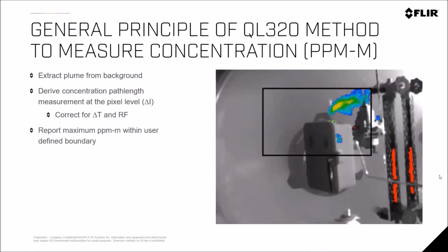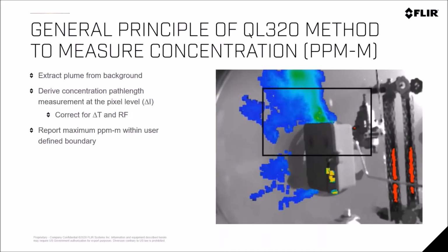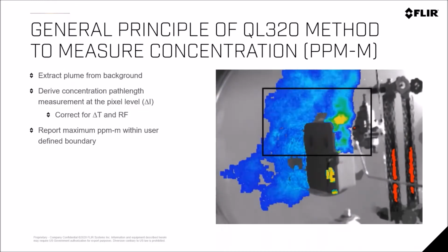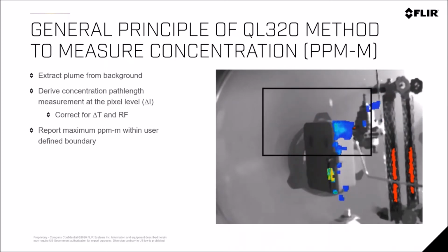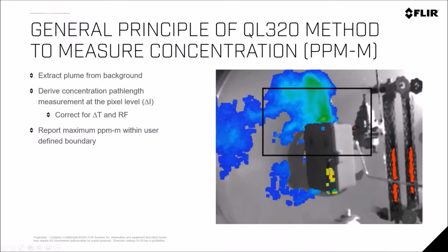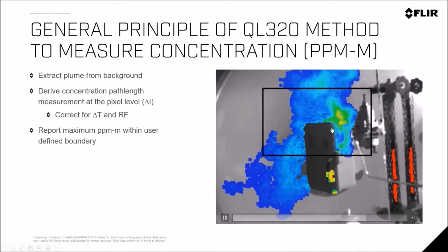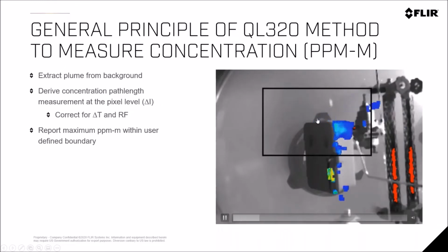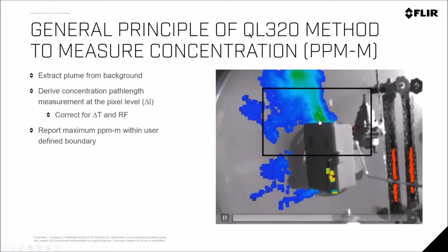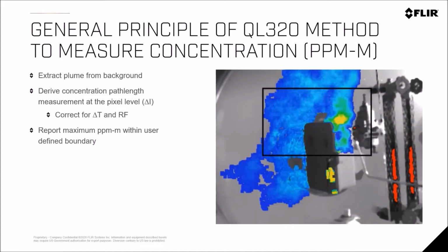The newer way for us to calculate and quantify optical gas imaging is through concentration. This is done in parts per million, or ppm, over an estimated 1 meter. And when we say 1 meter, it's not a meter from left to right or right to left, top to bottom or bottom to top. It's assuming that that leak is 1 meter in the 3rd dimension.